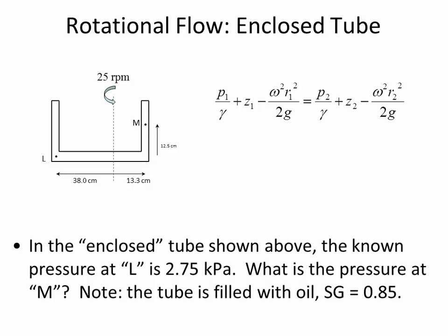So it's a lot of algebra and substitution between the two. Any hang-ups or questions about this example? If we look at the concepts involved, the message you should get is that even though the liquid level isn't allowed to rise or fall in this enclosed U-tube, the pressure still changed because of the acceleration. The pressure in the fluid was affected by this rotation.